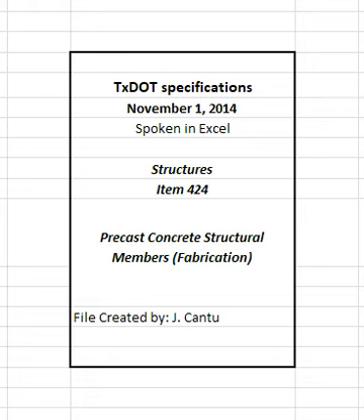Splice all straight strands in a multiple strand tensioning operation so an adjustment can be made for the average seating loss. Cut strand ends to be spliced with shears, abrasive saws, or grinders to remove regions where chucks were previously seated. Cut in the same manner at least 12 inches from strand ends to be spliced that were previously flame cut.